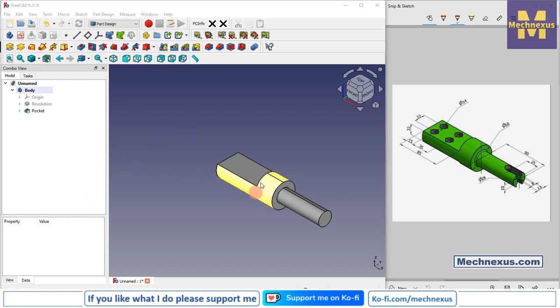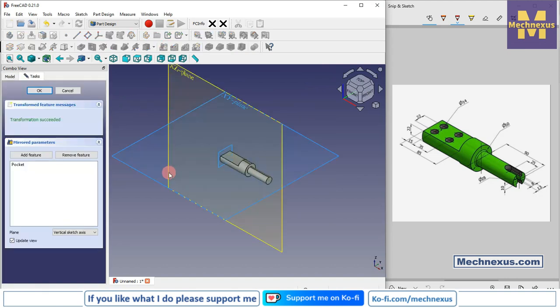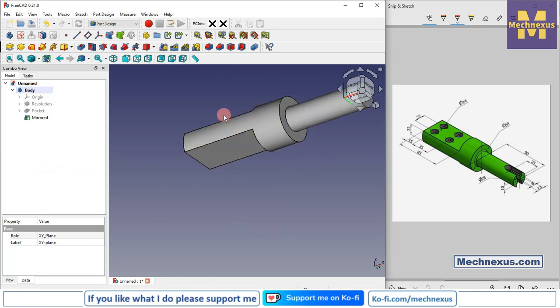And now we will mirror this cut on the other side. So for this we will select this pocket and click on the mirror icon, and from here we will click on select reference and we will select this plane and click on OK. So our cut got mirrored on the other side.